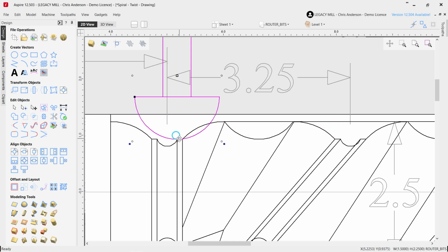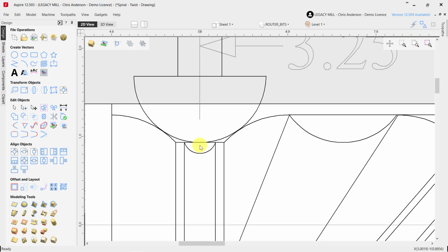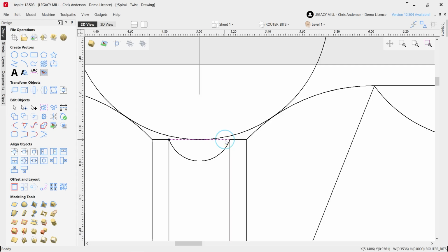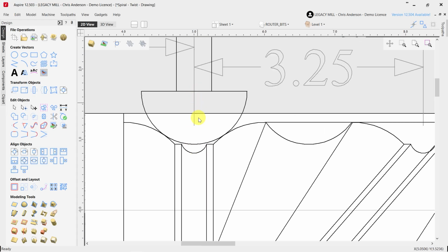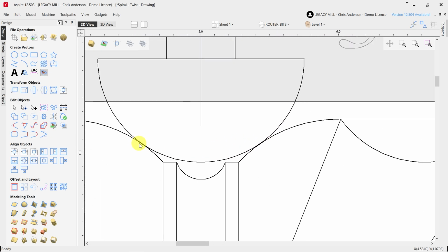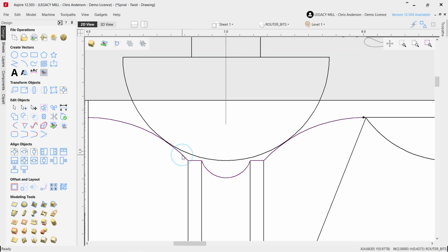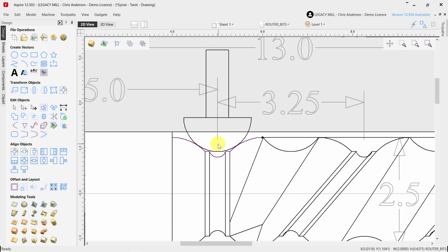So what I needed to make sure is if this was in the center, that's where the cutter is going to end up in space as it plunges down and then starts cutting. And you can see it's just enough to where it's not going to make contact with my profile cutter that's already turned around the circumference of my part.